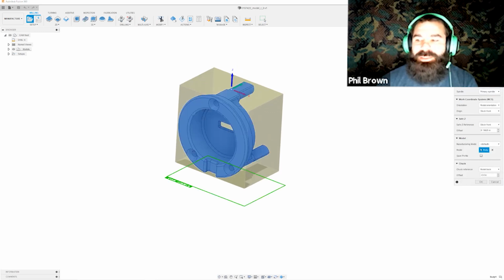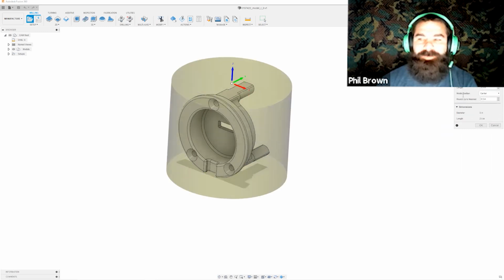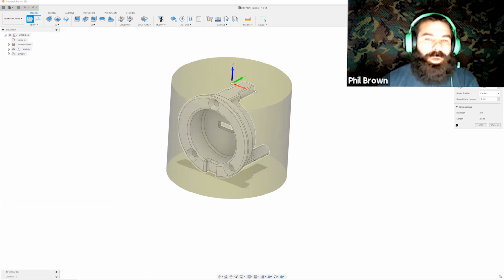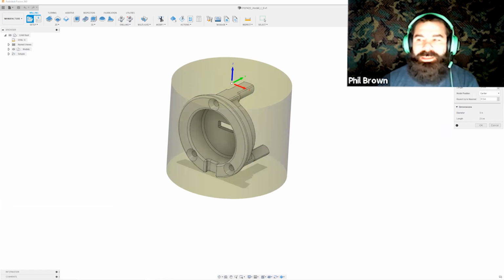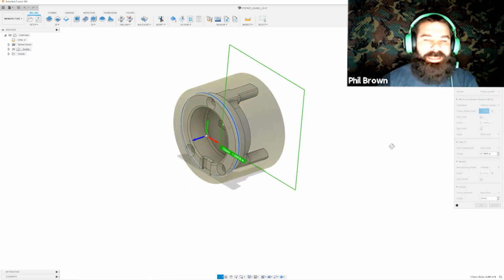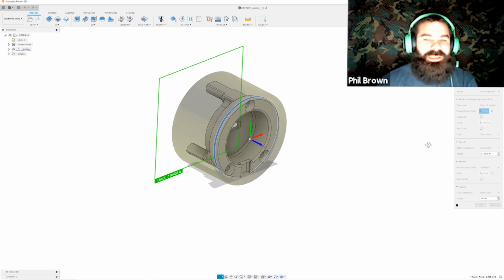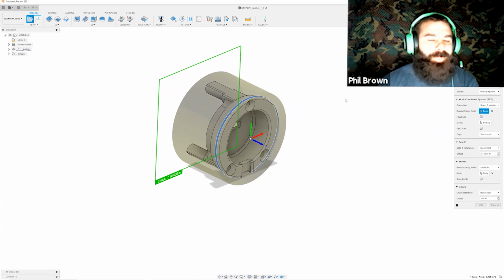And then I like to personally change my stock. So let's go to a fixed size cylinder and utilize that. Currently my cylinder is pointed in reference to my world coordinates. So ideally, would I have to go back and change everything in design? Not inside of Fusion 360. I can actually define whatever I want for my Z and my X. In this case, it automatically snapped to the outside cylinder radius of my part.